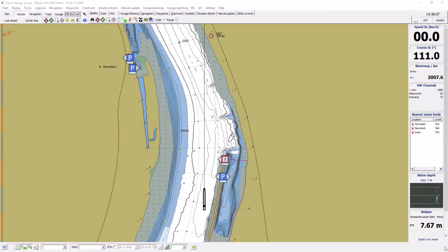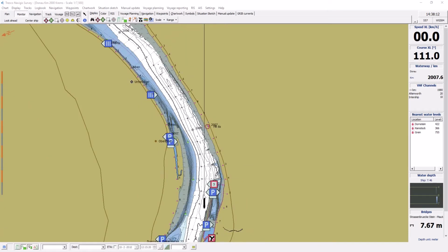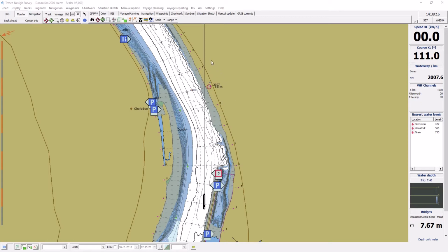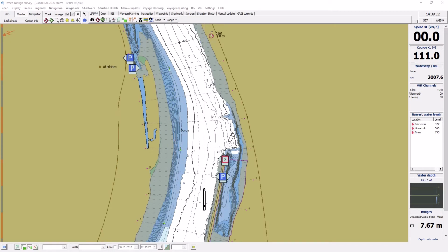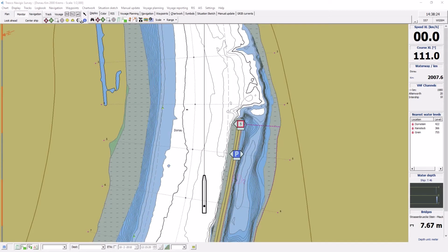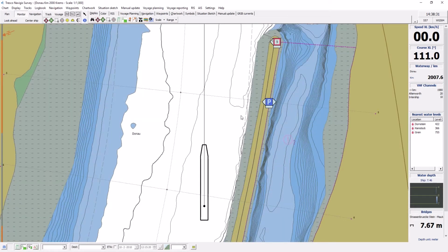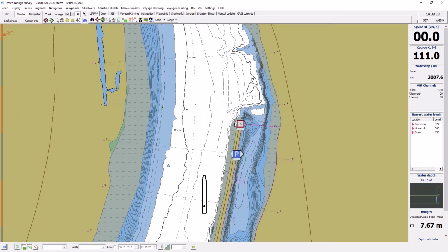The main panel of Navigis contains the Inland ECDIS chart, with information about the fairway, your own ship, and other vessels. On the chart, you'll see the fairway information with buoys and beacons. On the chart, you'll also find other information like traffic signs and distance marks. When you activate the information button and hover with the mouse on a sign, you'll see extra information. Further on, there are symbols warning for different dangers like shallow areas.